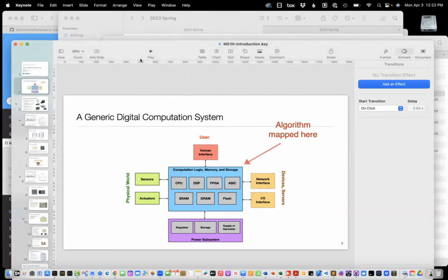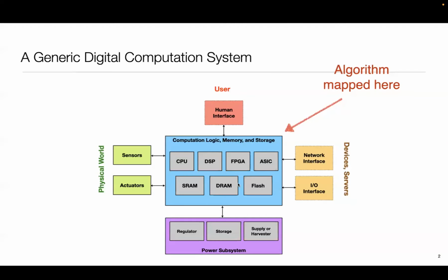Okay, then back out here, SRAM and DRAM, both of them, when you power down, they basically lose their content. Flash, on the other hand, is even denser, and very importantly, it's permanent. So if you want to remember things across power down, as well as they're used to store the program itself in case of CPU, we use flash.